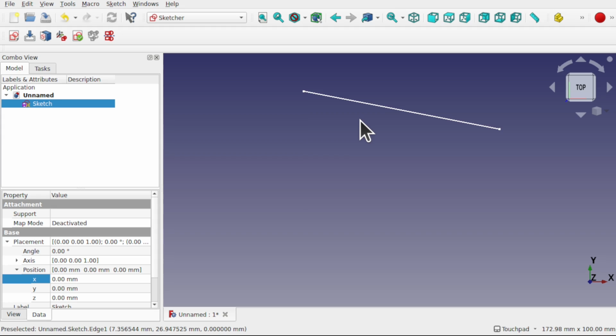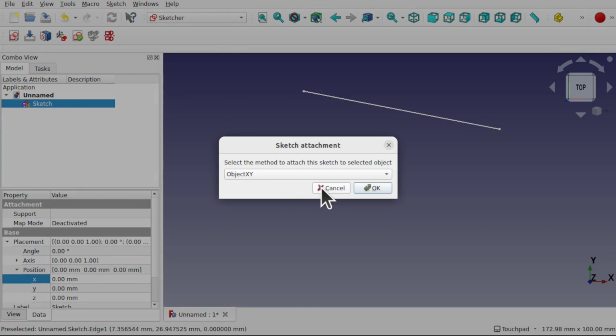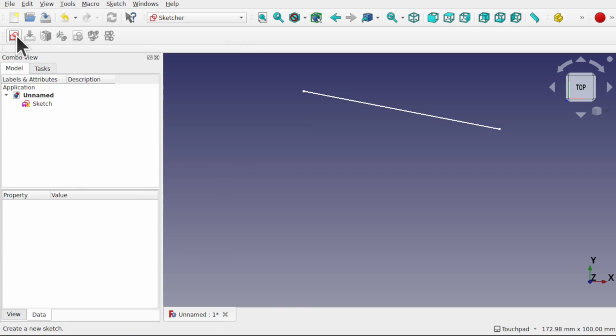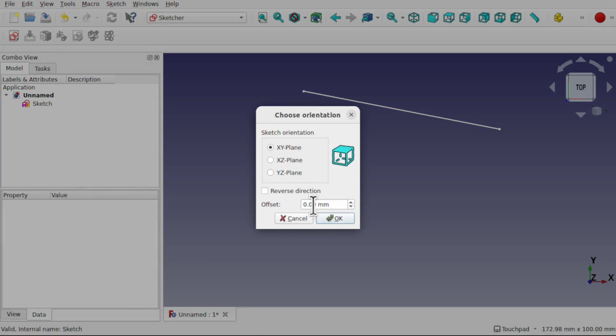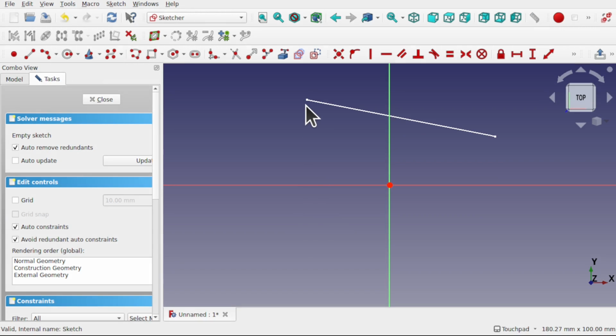We're now going to create another sketch to align the profiles, and this is quite important. So new sketch, make sure nothing's selected. New sketch, XY plane. Look at the beginning and end of this line. We're going to be using the point, which is not often used, and we're going to place these in line at different points for the profile.